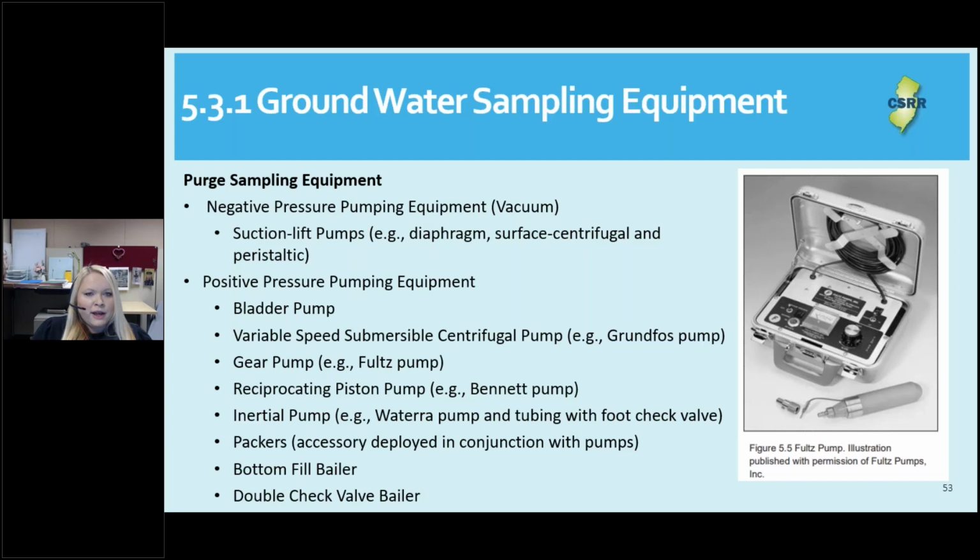With negative pressure, accurate and reproducible measurements of volatile compounds, organic and inorganic, and air-sensitive parameters cannot be obtained. This bias is extended to samples collected for, but not limited to, volatile organics, dissolved oxygen, pH, carbon dioxide, and iron. As a result, these types of devices are not recommended for the collection of samples for volatile organic compounds and higher vapor pressure semi-volatile organic compounds and M&A parameters.